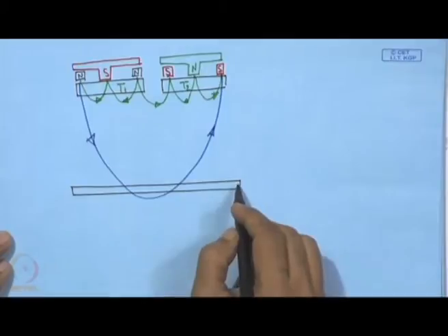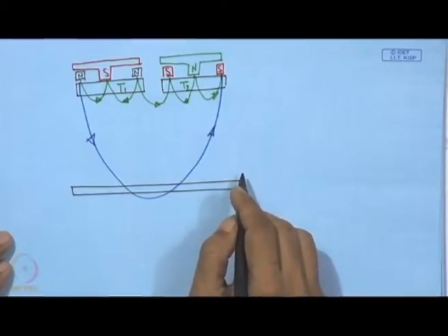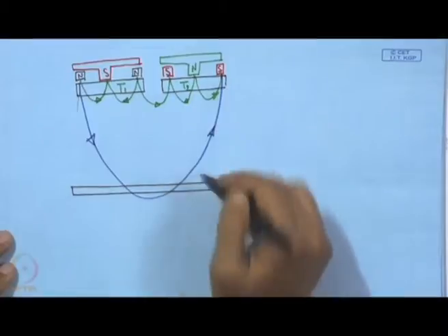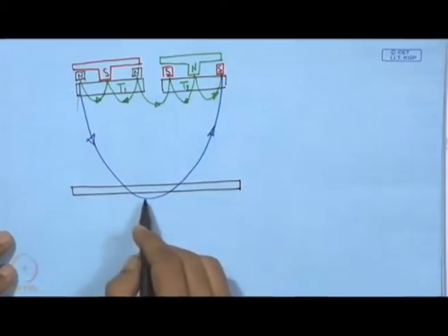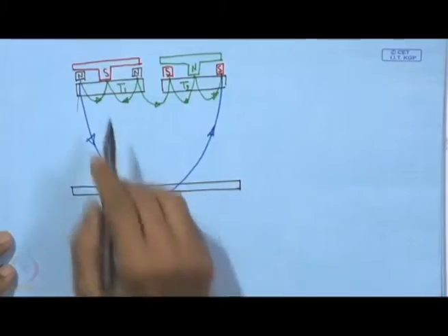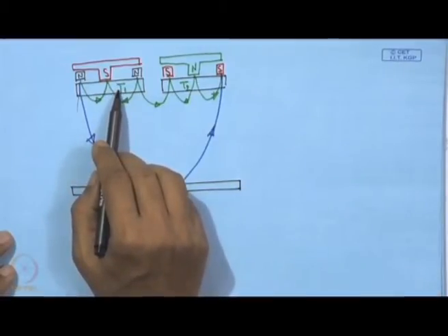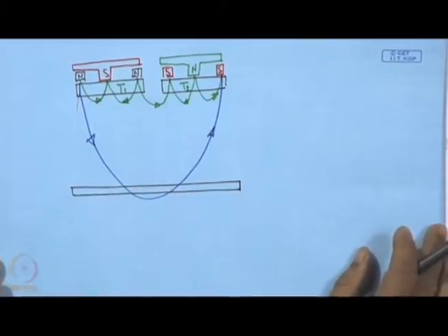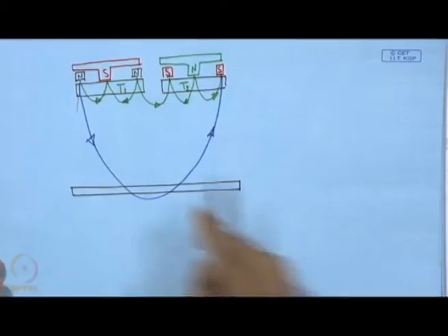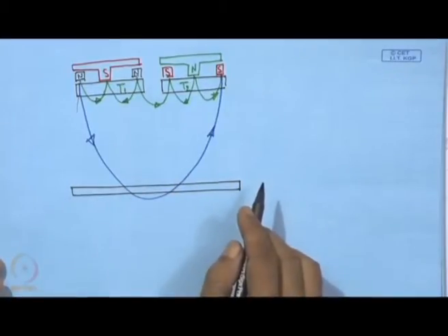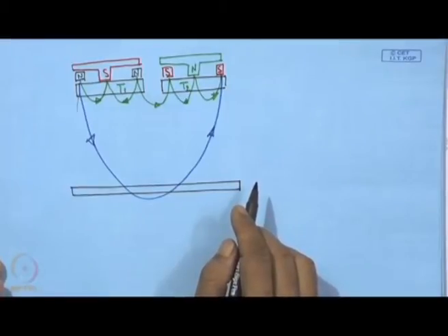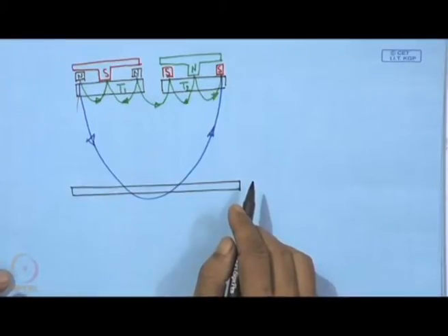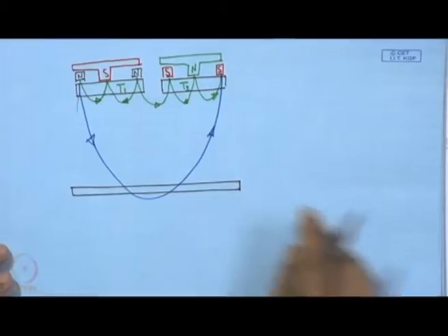So, if we have a large piece which needs to be coated, in that case we can have a large plasma volume in which the substrate can be placed, or we can have two materials and they can be properly combined to form one alloy or a graded structure on this flat large surface. And this is a dual target lying in the same plane and having a closed field unbalanced configuration.